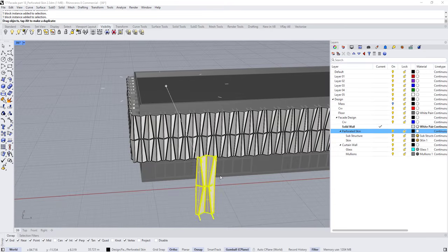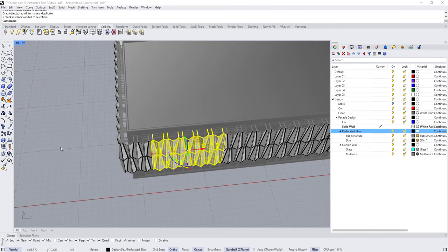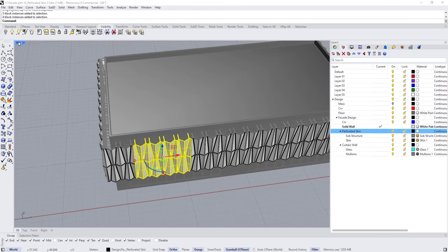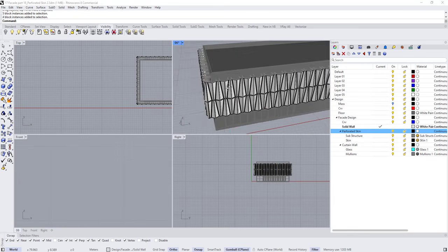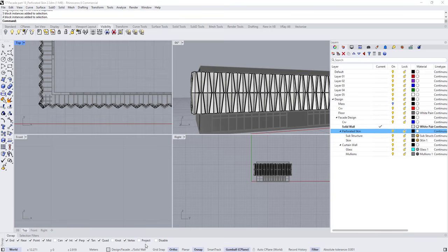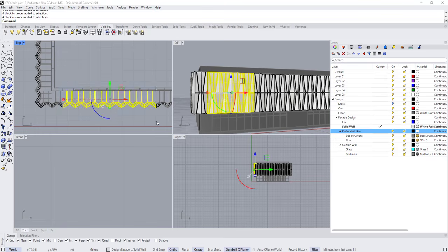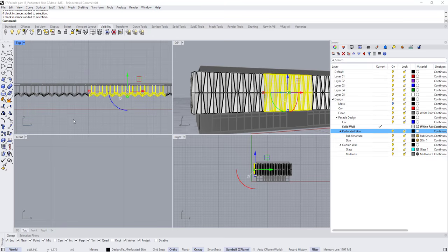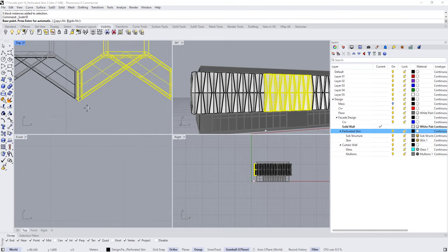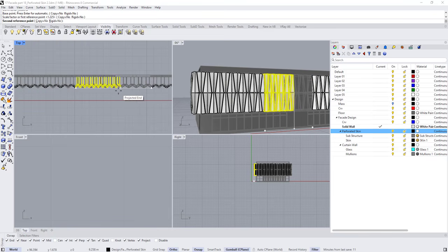So the first thing I want to do is testing variation, but without exploding the blocks. And so I'm going to start scaling using scale in one direction to create some kind of size variation. So let's do this adjustment in the top view, while keeping this opened. So I'm going to open the project. Let's come here to top view and select maybe starting from the middle. Select a few blocks and let's choose scale in one direction and let's scale it from here and start maybe moving it a little bit like this.